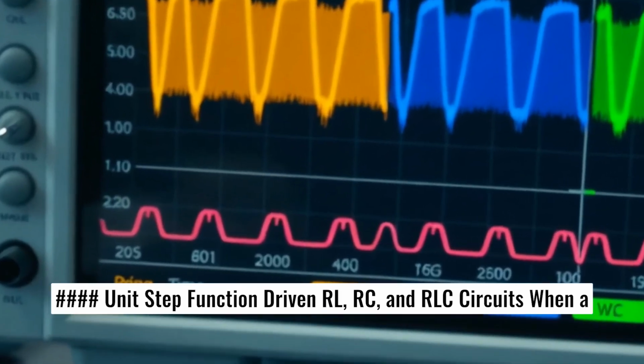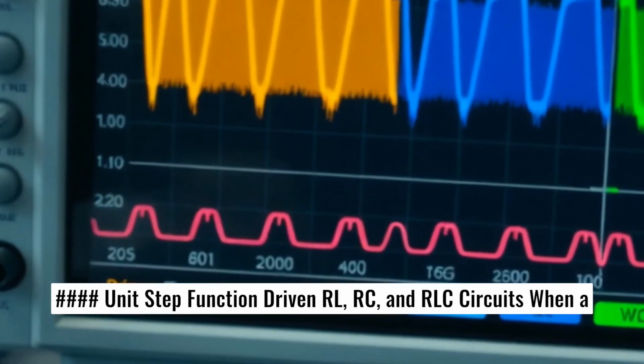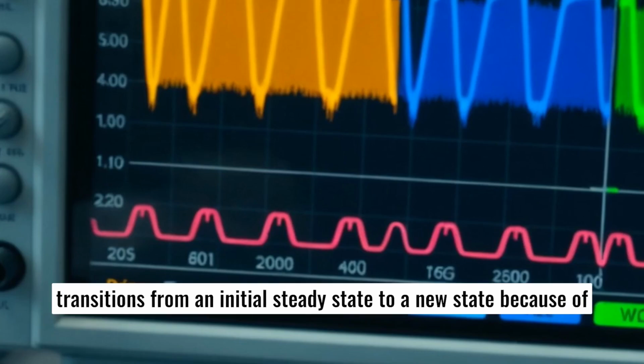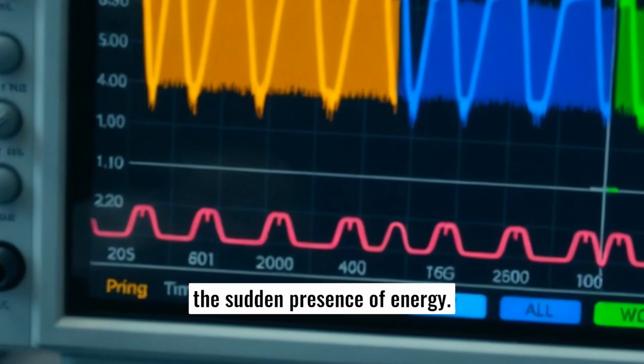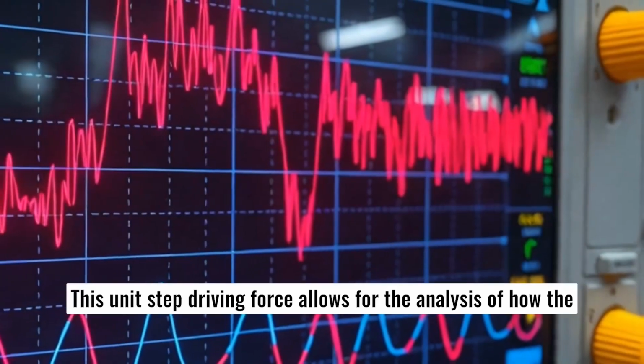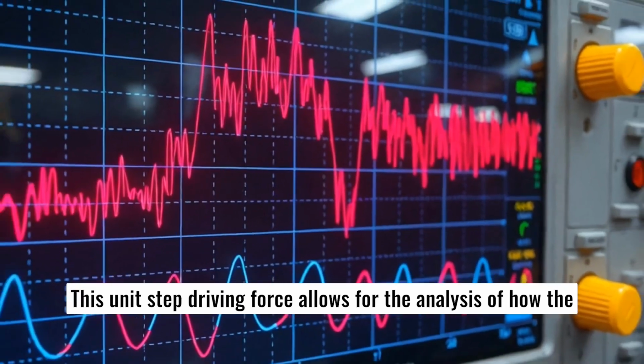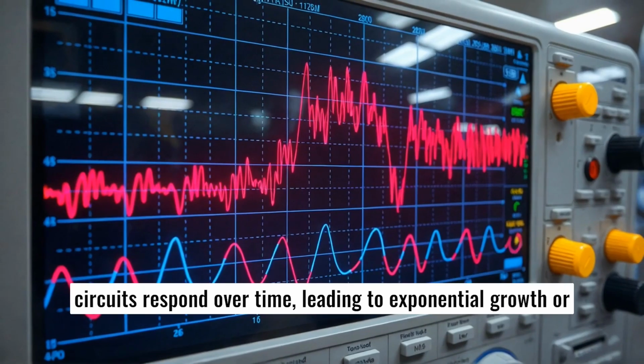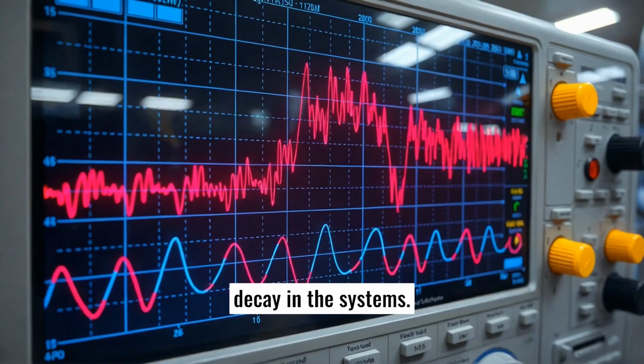Unit step function driven RL, RC, and RLC circuits. When a unit step function is applied to an RL or RC circuit, the system transitions from an initial steady state to a new state because of the sudden presence of energy. This unit step driving force allows for the analysis of how the circuits respond over time, leading to exponential growth or decay in the systems.